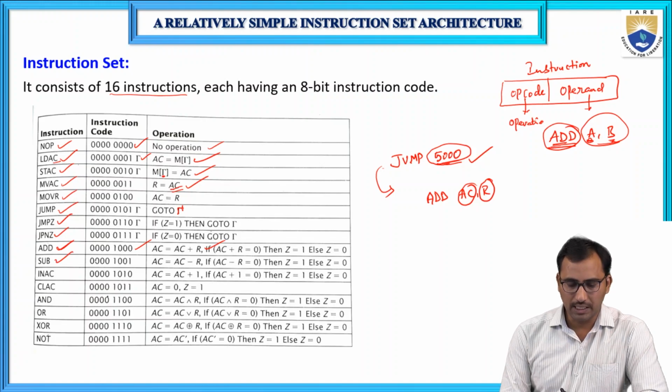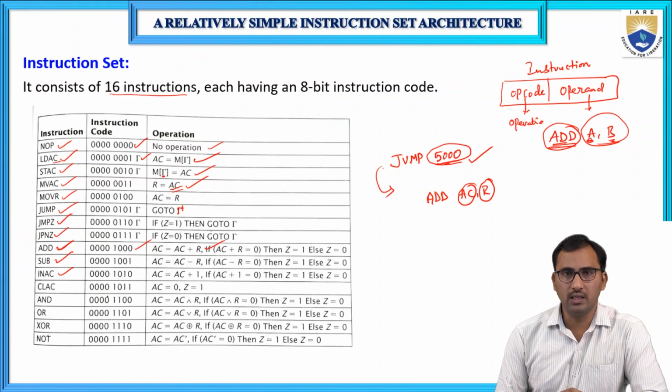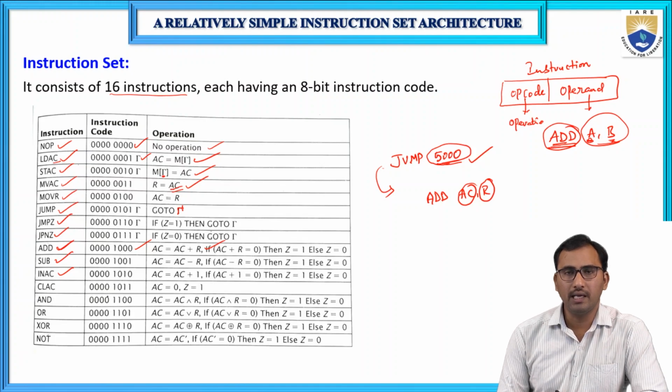And the next, subtraction. SUB means subtraction. Increment, INAC, increment accumulator. That means this particular instruction will increment the value which is stored in the accumulator by 1. Suppose the accumulator contains a value 5, then after incrementing it will become 6.